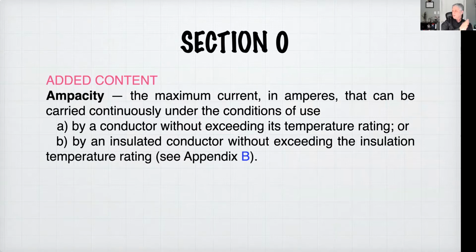So temperature rating is either based on the insulation or by the termination temperature rating. Section 4 addresses this, and section 4 applies the demand and calculations to apply an ampacity to a conductor based on insulation or termination temperature rating, or TTR, based on the temperature rating of the breaker or load or whatever it may be connected to.